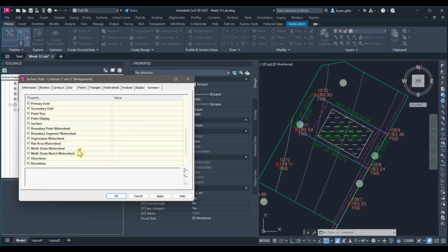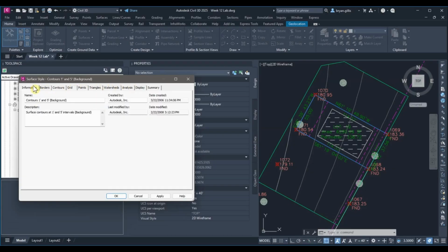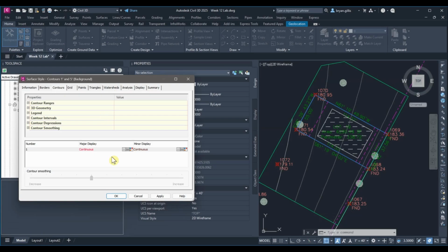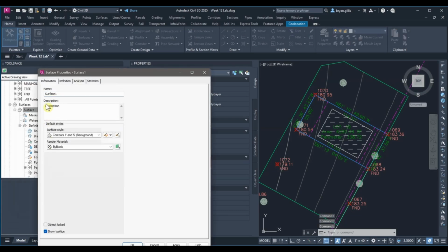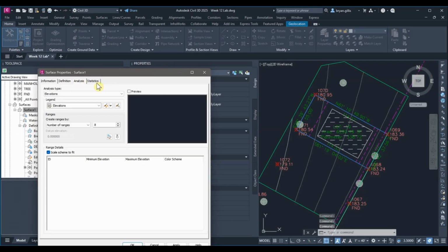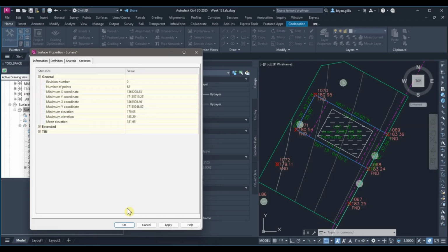So what I would recommend doing in an instance like this is I'm going to pull this surface off of my final plat. I wouldn't include it in the plat itself, but I would include my max and min elevations as part of my general notes. I would include it in my survey report. I would provide the slope information across our entire lot.